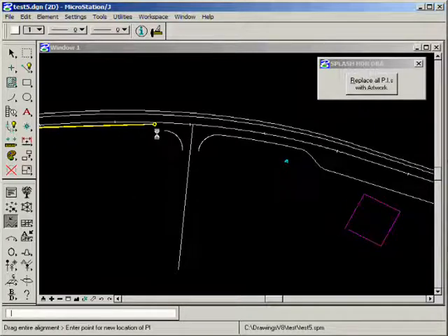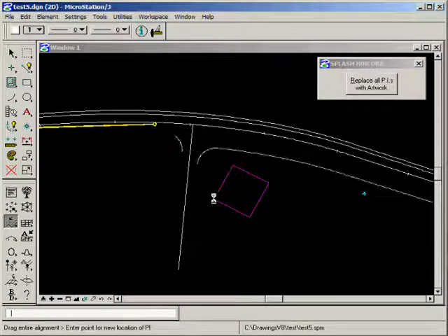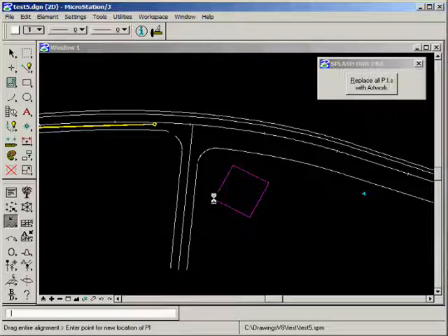and we see that we now have a normal looking intersection, and the widening of the pavement is far away from the intersection. As we bring the building, which causes the pavement widening, closer to the intersection, we see that it affects the fillets.